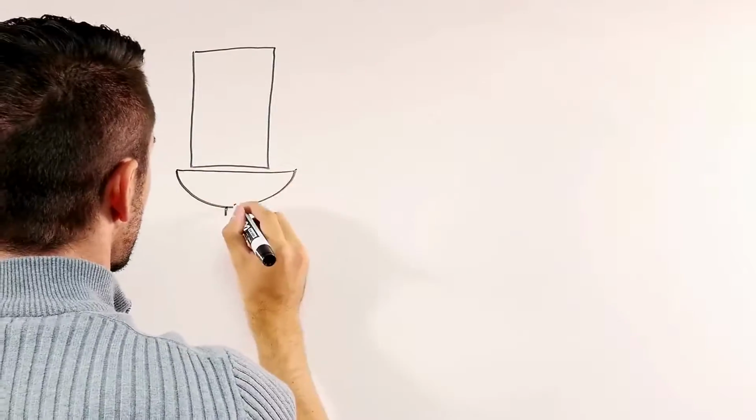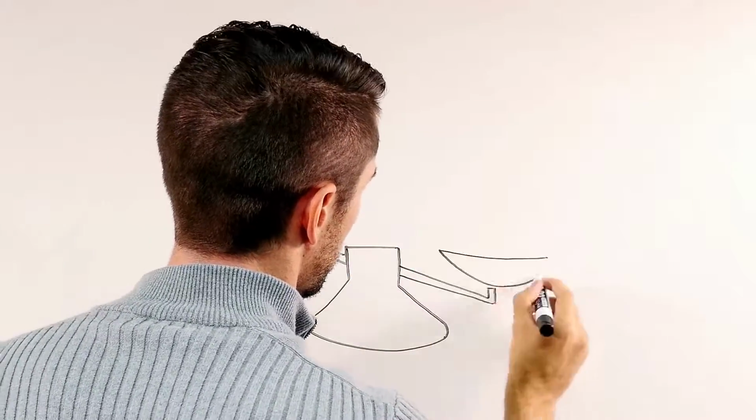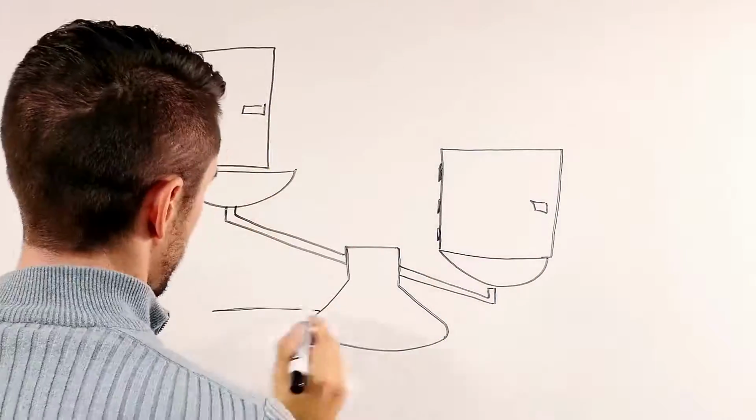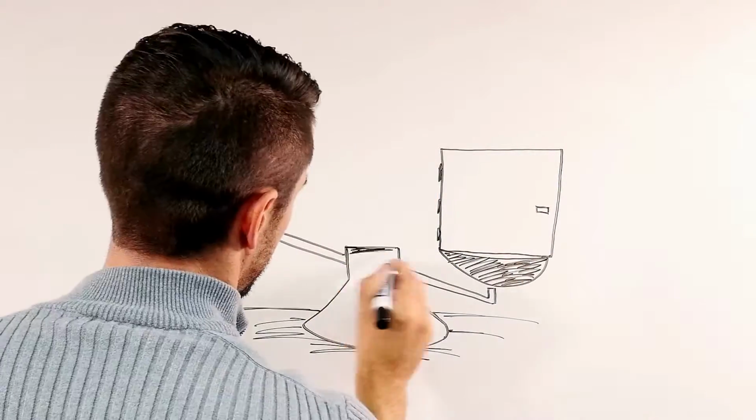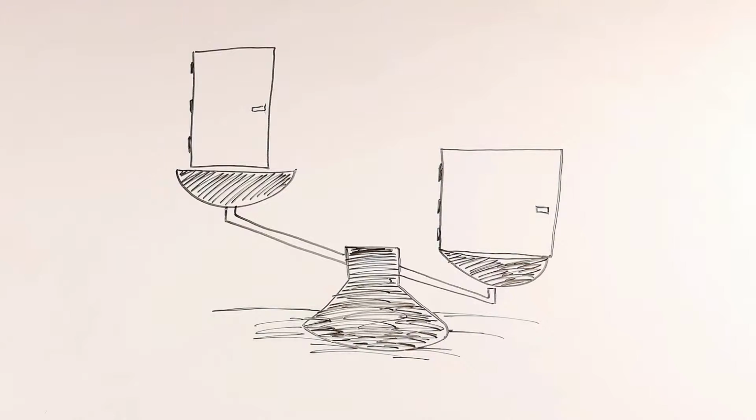Hinges are also categorized according to standard or heavy weight. As shown in charts and hinge catalogs, the weight of the door and the frequency of use determine if one should choose a heavyweight hinge. Heavyweight hinges are thicker and have more anti-friction bearings than standard weight hinges.